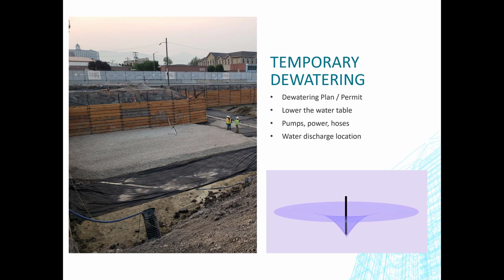We had to do the same thing at Bear River Bird Refuge. We had a pretty good settling pond that we built, probably half the size of someone's swimming pool in their backyard, maybe not nearly as deep, maybe a couple feet deep. We dewatered into that, let the water settle, and then it had a weir on one end of it, so that the water went over this weir and into the Bear River drainage area.